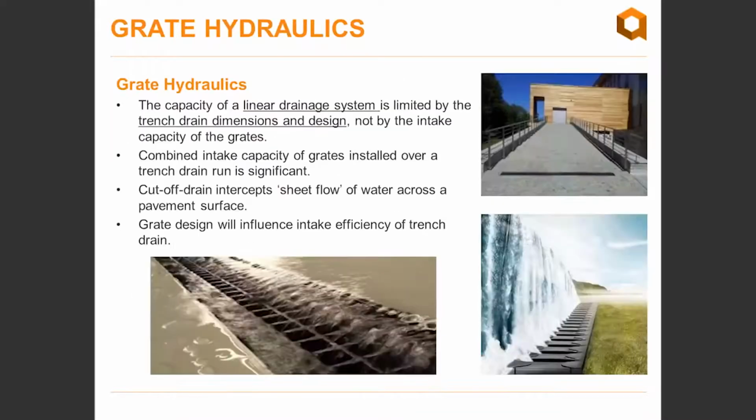Another aspect with the hydraulics is the grate hydraulics. Very important, the capacity of a linear drainage system is limited by the trench drain dimensions and design, not by the intake capacity of the grates. So with just a few meters of trench drain, the channel capacity will be less than the grate intake capacity. So keep that in mind.